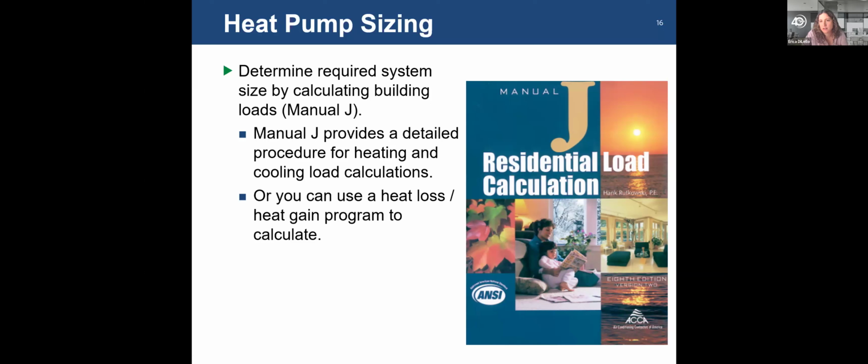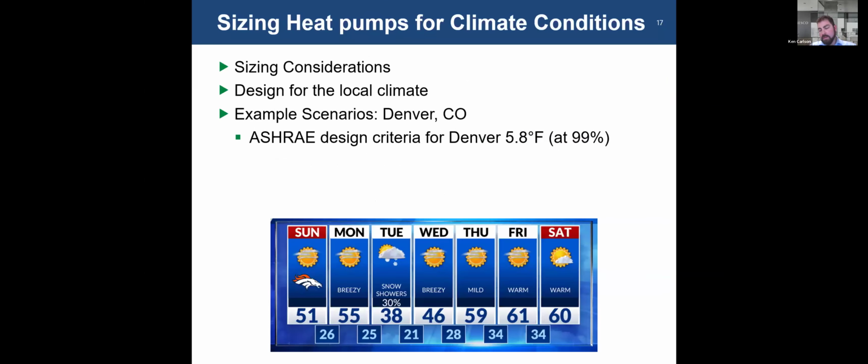In the slide number 9 example, how did you account for heat pump operating costs during cold weather run hours as heating capacity decreases with lower ambient temperatures? Okay, so for the heat pump cost, we used a COP of 3. I didn't run an evaluation to get a COP throughout all the bin hours plus the resistive heat. The COP on most heat pumps goes down to about 2 when you get to low ambient conditions, and then you would need your electric resistive heating on top of that, creating an even lower COP.